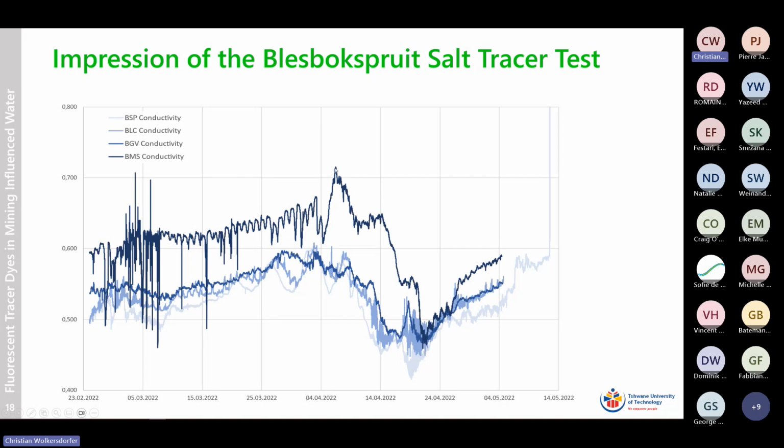And then we heard it in the previous talk already. The longer the flow distance, the smaller gets the peak. So here you can see it again, here you can see it again, and the light one is somewhere here. So we used correlation analysis to find out where and how the peak is moving along the stream. So that's just a pre-test. This test will, when we start in about 4 to 6 weeks, use 100 kilograms of tracers, 33 kilograms of uranine, eosine Y, and tinopal CBX.